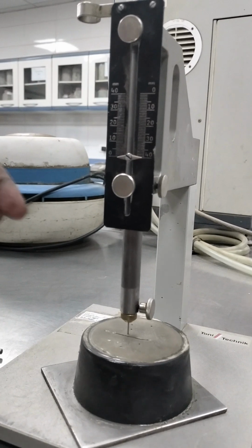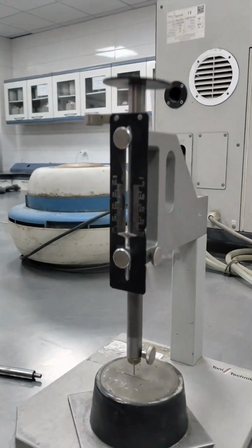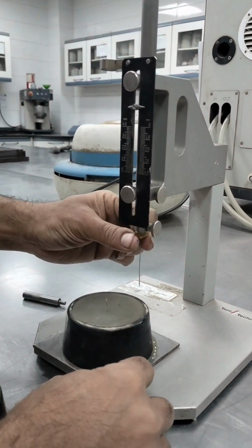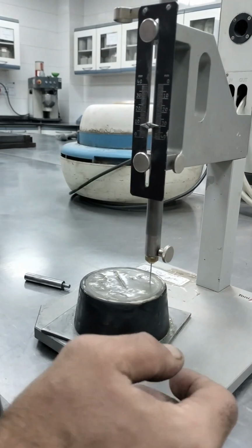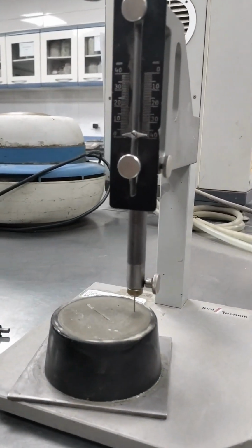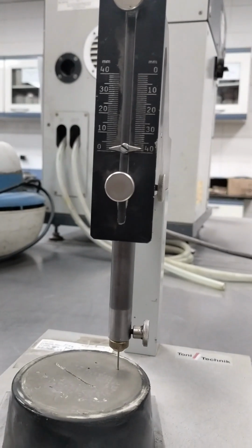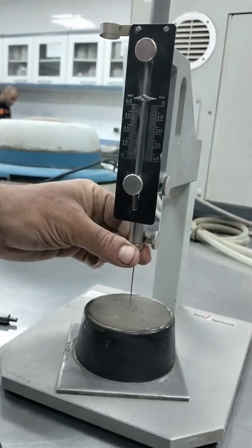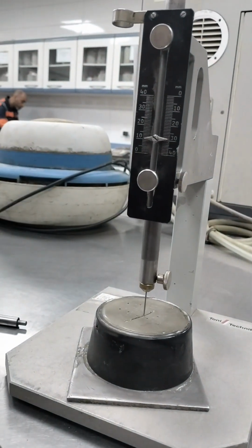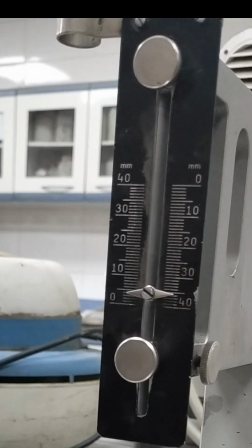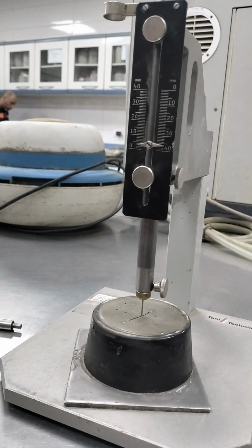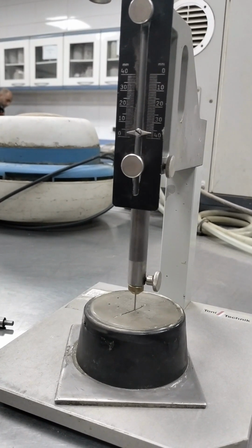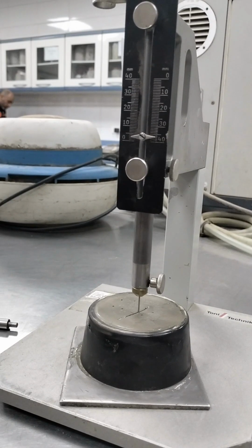Whichever is the earlier. Repeat the penetration on the same specimen at conveniently spaced positions, not less than 8 mm from the rim of the mold or 5 mm from each other, and at least 10 mm from the last penetration position, at conveniently spaced intervals of time, e.g. at 10-minute intervals, to get penetration readings of 6 plus or minus 3 mm. The time elapsed between 0 time and the time at which the distance between the needle and the base plate is 6 plus or minus 3 mm, measured to the nearest minute, is the initial setting time of the cement.